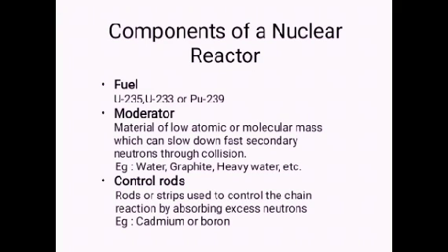And the third one is control material. In order to ensure that the fission chain reaction never goes out of control, certain non-fissile materials are used to absorb thermal neutrons. Cadmium, boron, etc. are typical examples of control materials used in reactors. Rods or strips of these materials, often incorporated with other metals or alloys, are located near the reactor core and pushed in mechanically whenever the neutron flux increases beyond a limit and then pulled out after control is achieved.